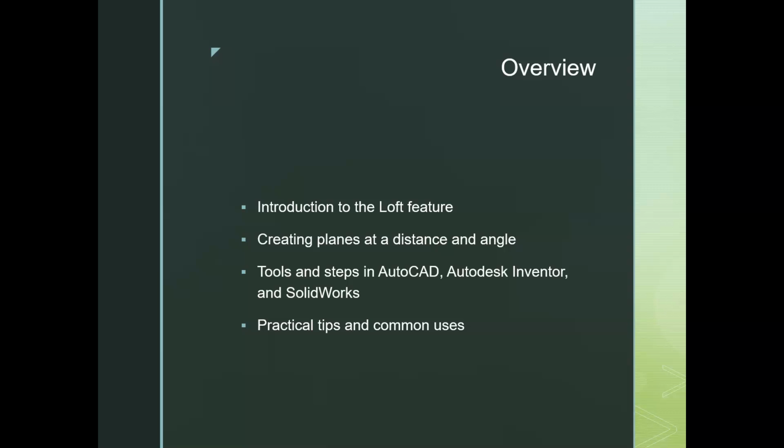Okay. Now, the other thing we discussed was the revolve command. Remember, with the revolve command you need two things. You're going to need that profile again, and that's common amongst all of them, and then we're going to need an axis of revolution. So that covers the extrude command. We got the revolve command, and then the sweep gets a little bit more complex, right? With the sweep command, we still need that closed profile, but we have to give it a path. And here is the Loft command.